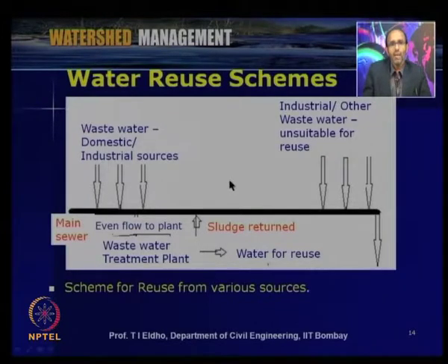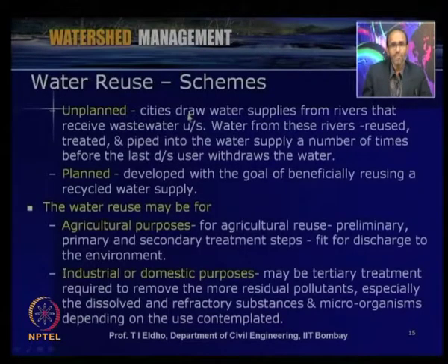So when we look into the water reuse schemes, we have to study the various aspects like the quality of the wastewater, from where we are taking the wastewater, what kind of treatment is to be given, and what will be the intended reuse. So like that we have to plan the reuse schemes. When we look into reuse schemes, as I mentioned, it can be unplanned reuse schemes or planned reuse schemes.